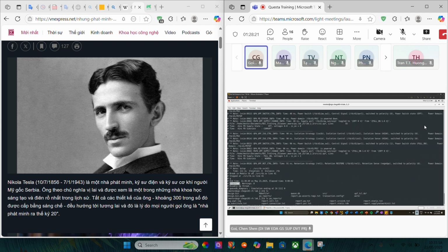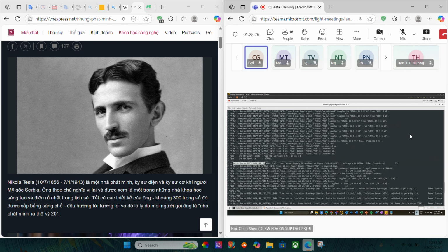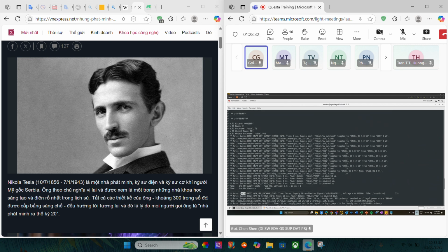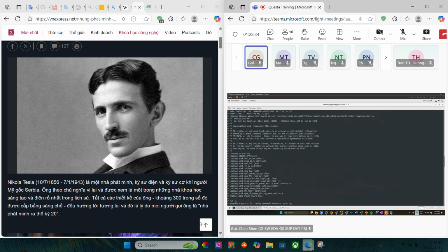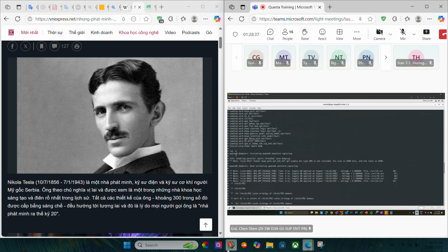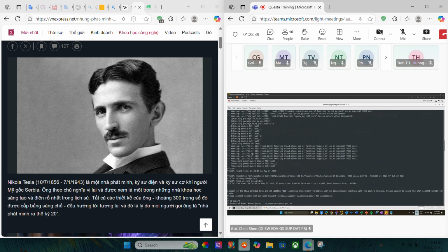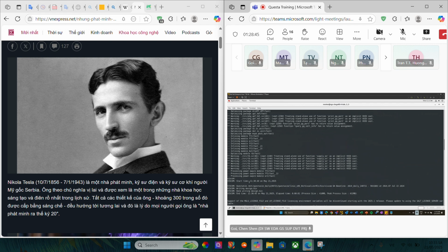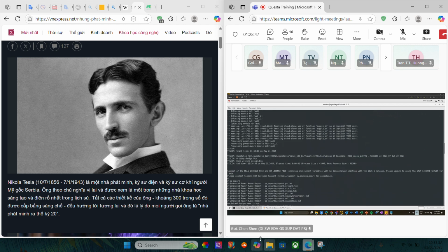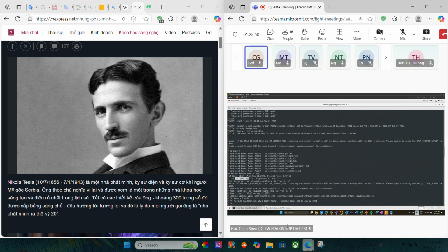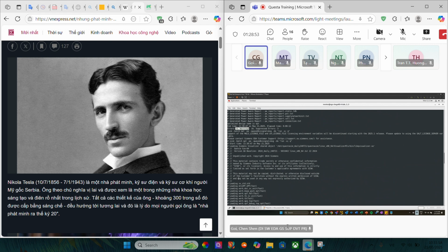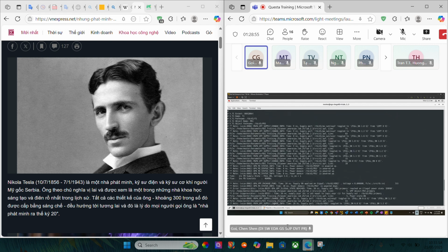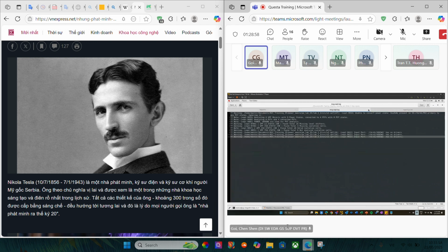We have two errors, and we scroll up from our terminal. Okay, the error is in vsim. We can see the error is in simulation, but let's scroll up further to check on vop. Okay, seems like vop is running fine and there's no error from vop. So this vop.log message file is not helpful and we need the vsim.log file.